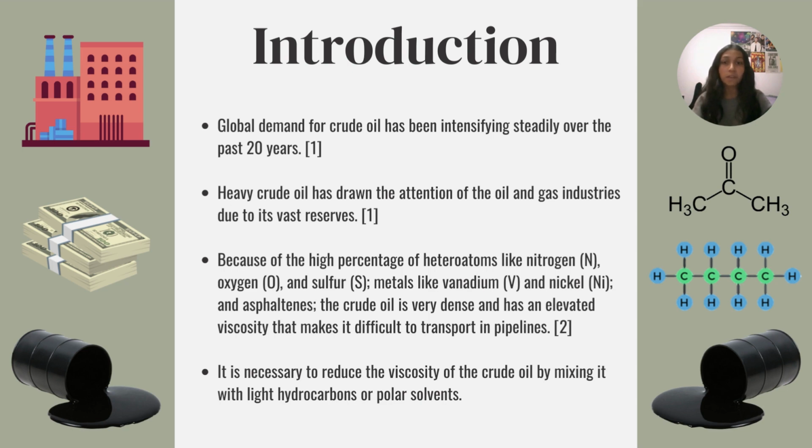in pipelines. For this reason, it is necessary to reduce the viscosity of the crude oil by mixing it with light hydrocarbons or polar solvents. But how can this substance decrease the viscosity of crude oil?